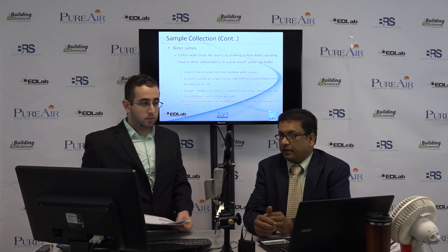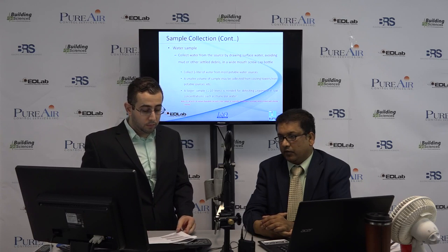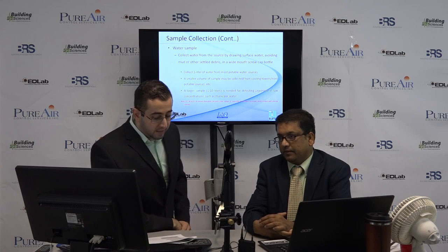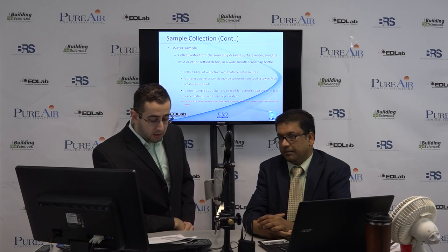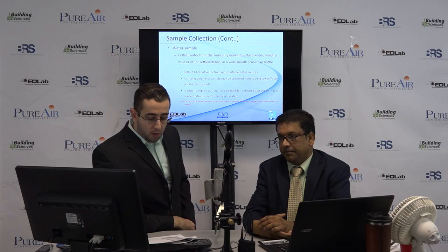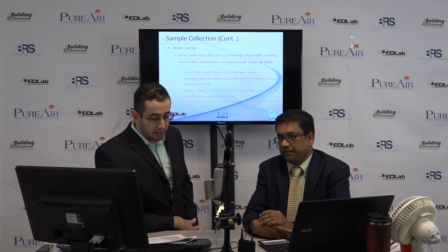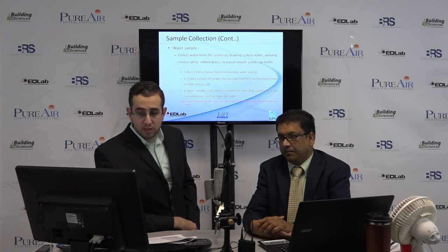Well, that's very well, but can you go ahead and elaborate on how much water one should collect for testing for Legionella and how they should be collecting those water samples? Of course, and this is important. Water is drawn from the surface of the source, and you want to try for the most part to avoid any other debris, something like mud or dirt or anything along those lines that could get in and affect the sample. You typically want just water when it comes to collecting Legionella. You want to collect 1 liter of water for most potable water sources.